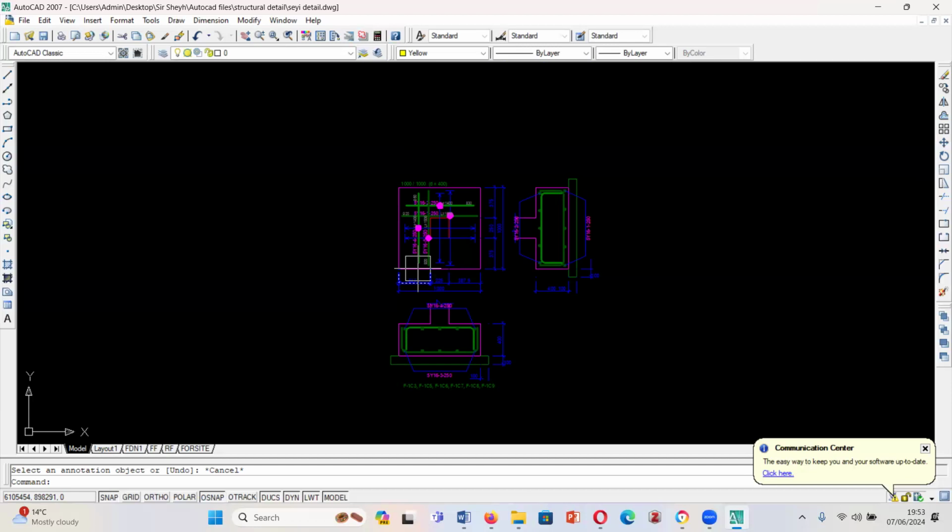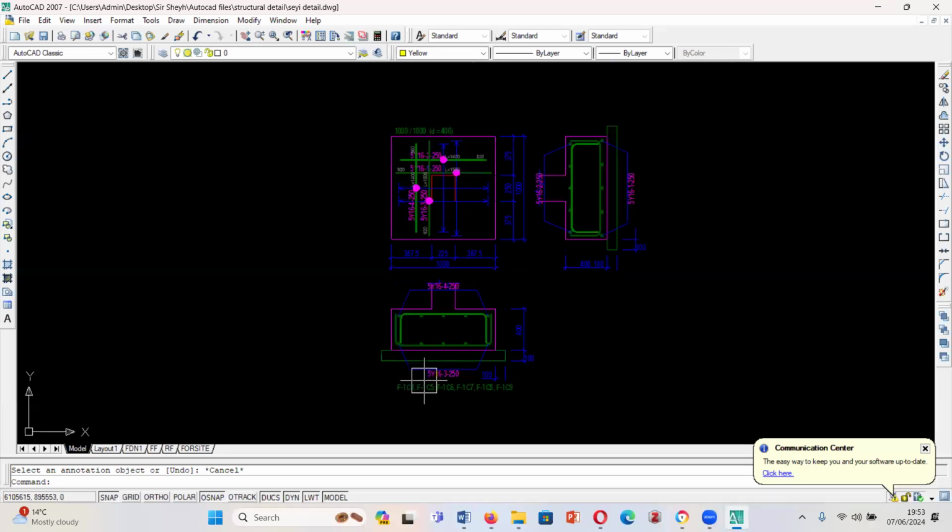What can you say about what you are seeing? I can see the reinforcement, the concrete cover. Okay, so what's the concrete cover? The concrete cover is the small portion where the concrete fits the formwork. No problem, I understand you. That's the portion between the face of your reinforcement bar and the external part of your concrete, the face of the formwork. I get it.